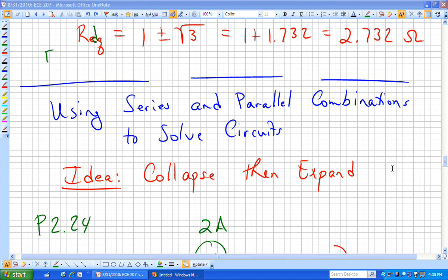So are the voltage drops V1 and V2 the same as the voltage drops through R1 and R3? V sub 1 is the voltage dropped across R1. It's also the voltage dropped across I sub A. V sub 2 is the voltage dropped across R sub 3. So if we needed to find the current through R sub 3 coming down, it would just be V sub 2 divided by R sub 3. V sub 3 is the voltage dropped across that current source.